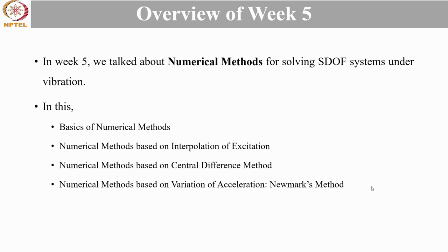All different responses means displacement, velocity and acceleration at a particular time step. And in the final module, module 4, we saw the numerical method based on variation in acceleration, also known as Newmark's method, which among all three is the most used one, wherein the change in the response between two time steps is estimated first and then used for calculating the response ahead. So moving ahead, we will brush up all the formulas and relations we saw this week so that everyone can understand the numerical and MATLAB part coming ahead properly.